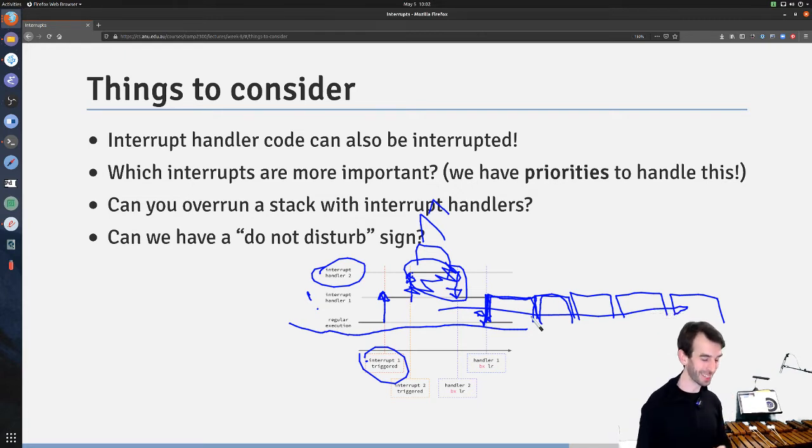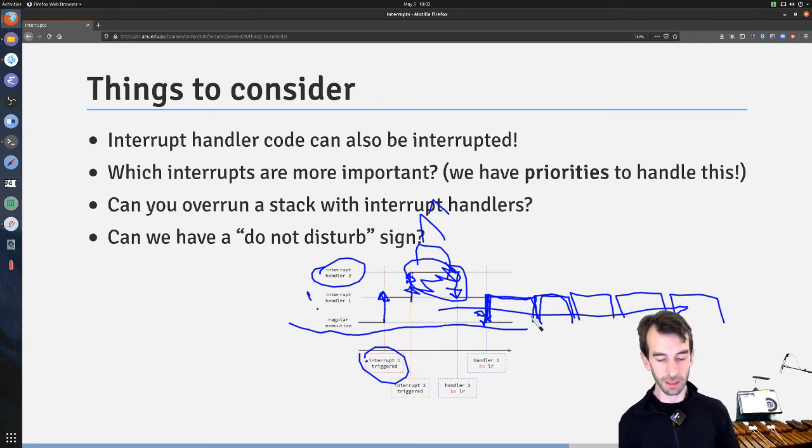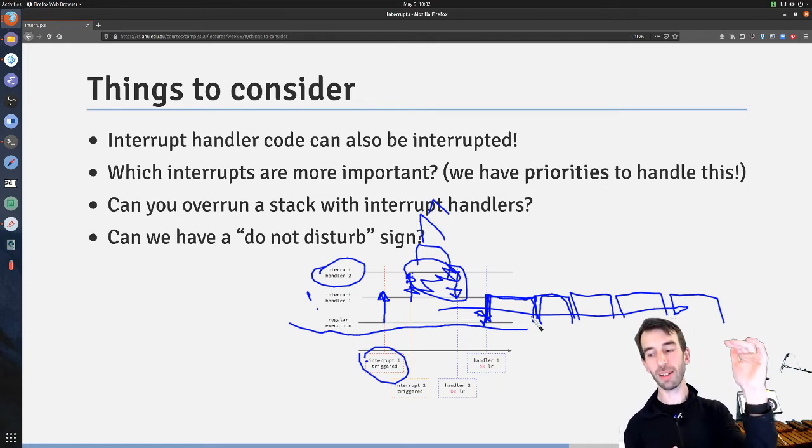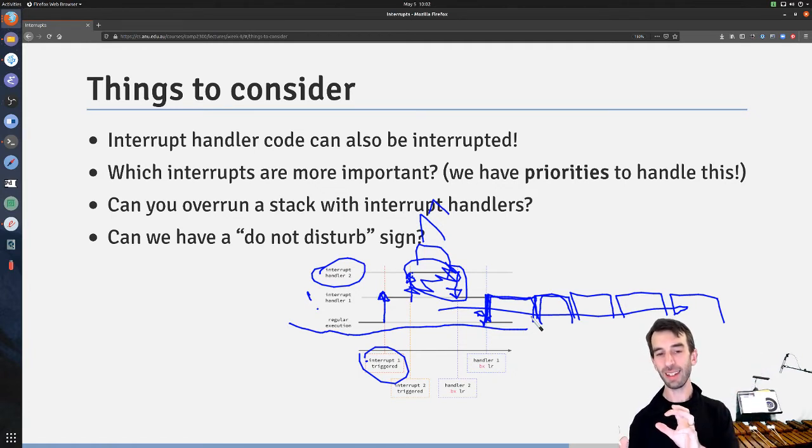I just said blocks, and that means that we've run into the first time in which we have to consider asynchronism in our Disco board programs. Which is a sort of exciting time, right? We can't just consider our program execution happening in order in the code in memory. We have to consider what events might happen and the time they might happen, and will that result in our program being broken or not broken?